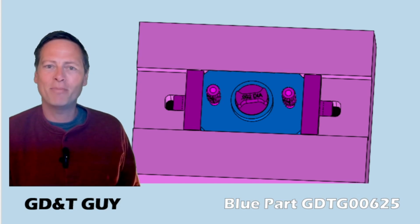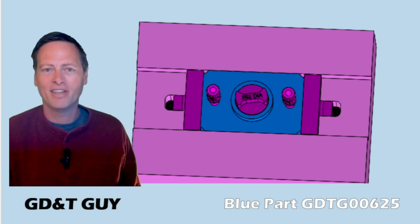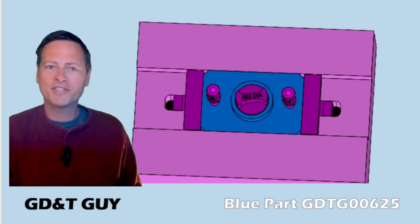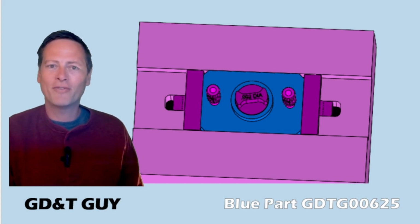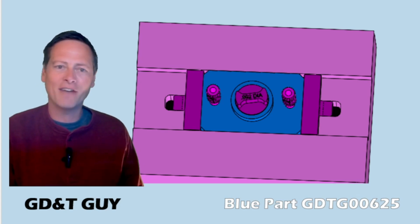Another thing that bothers me about this one has to do with the way the Datum C simulators come together to make contact with these ends and center the part. This is similar to some of the stuff I've been saying all along, only worse. How do we continue to call this a one-DOF tertiary datum feature? And then the Datum B simulator groove, with a few thousandths of clearance, how do we continue to call that a 2-DOF secondary datum feature in this setup?